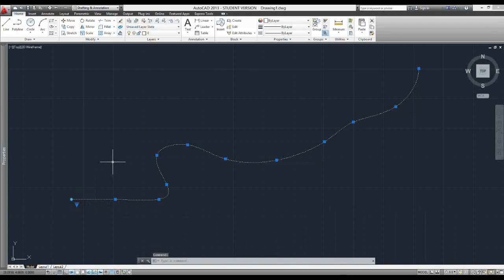Okay. One thing it does, though, if you have hard tangents on a spline with control vertices, it will not convert appropriately to a fit curve, because you may notice I lost my hard corners that I had at first. And if I just try going back, it's not going to give it back to me. I have to undo that point to get those hard points back.